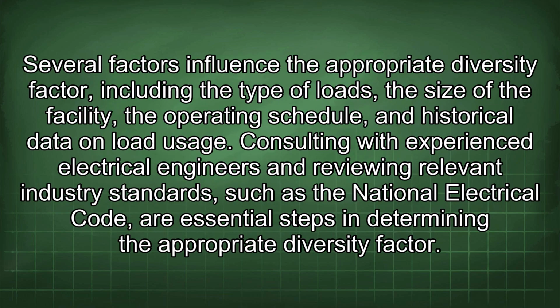Several factors influence the appropriate diversity factor, including the type of loads, the size of the facility, the operating schedule, and historical data on load usage. Consulting with experienced electrical engineers and reviewing relevant industry standards, such as the National Electrical Code, are essential steps in determining the appropriate diversity factor.